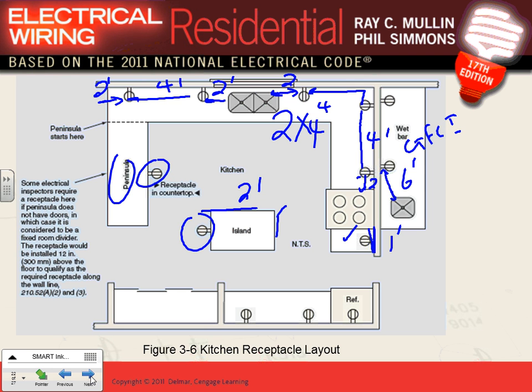Unless your garbage disposal is hardwired, you throw a GFCI. Ah, thank you. No, the GFCIs are on the countertop. Below the countertop, no GFCI required. Garbage disposal, dishwasher. Say we have a garbage disposal and dishwasher underneath here? Non-GFCI because you're under the countertop. The circuit breaker for the microwave. You have a microwave high, no GFCI for it. Only the countertop ones.